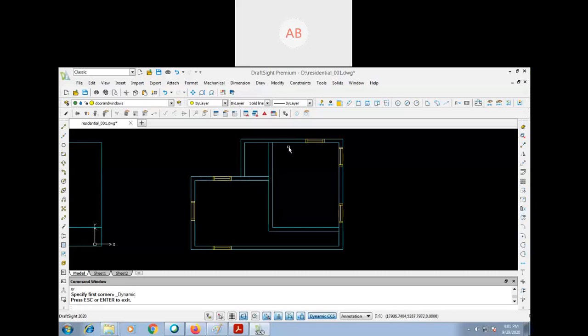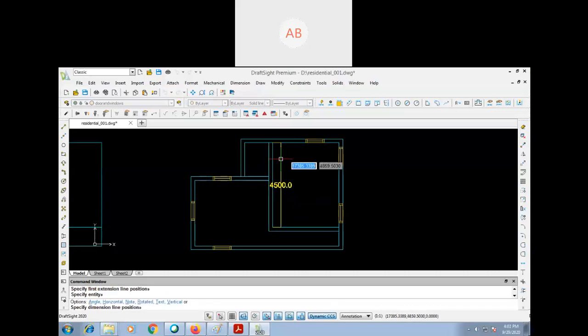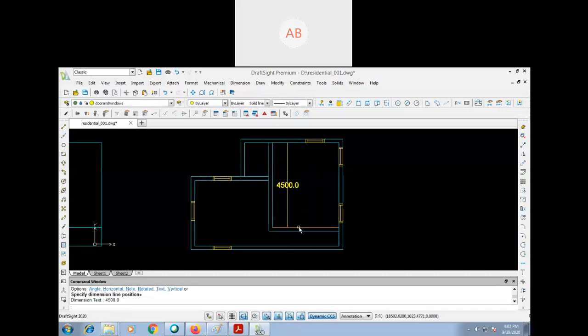Actually, the inside dimensions are given in the line drawing, so that is being mentioned. So it is supposed to be the room or the floor spaces. So if you look at the first inside measurements, it should be 4,200 into 3,500. So you are right. So if I look here, this should be 4,500, which is correct, and this should be my 3,600. You see the drawing. This should be the inside dimension. But the problem is, this side the room dimension will be different in that case.